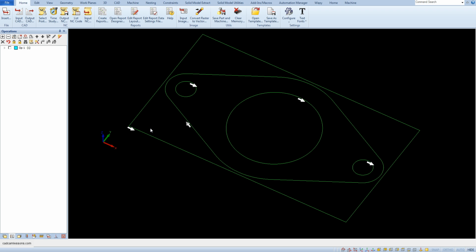If it was necessary to change the location of the base, it was also done by indicating its beginning on the model. Later, when I started working with Alphacam, it was hard for me to change that we don't move the coordinate system, only everything else, geometries and toolpaths. Therefore, someone who has worked in a different system and is switching to Alphacam may be surprised by this approach. You can get used to it quickly and this is not a problem.